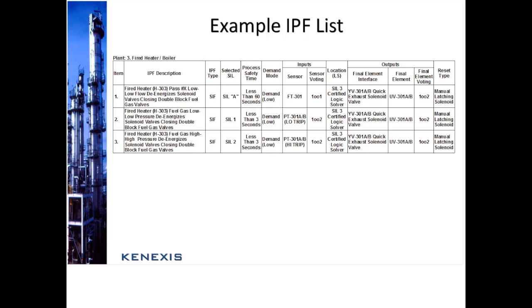The demand mode of the SIS is low, so we don't expect to see a demand on that safety function greater than the testing interval at which the function is given its full functional test. We have the input, we have the sensor tag names and information, whether it's the low trip or the high trip. Sensor voting, the first one there is a 1 out of 1.